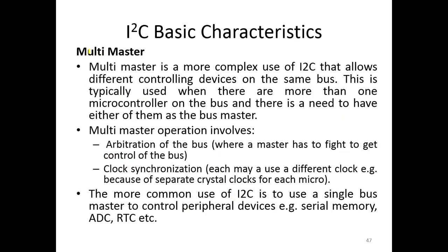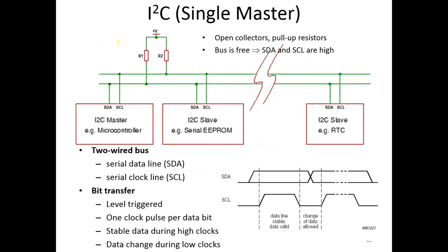So the multi-master process, if you have more than one microcontroller, okay? So generally we have one microcontroller with another device. So it's rare that we use the multi-master. So if you have multi-master, we need to use arbitration, okay? So this is how to make the connection.